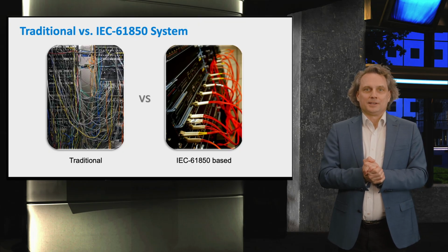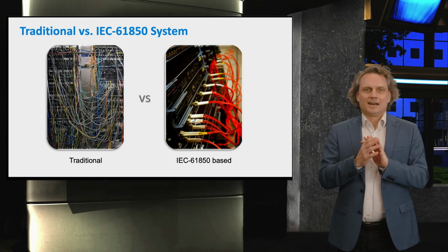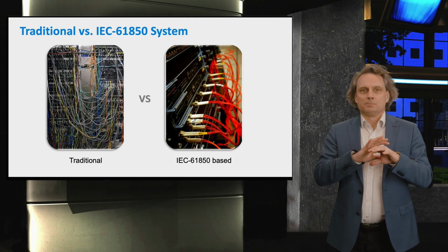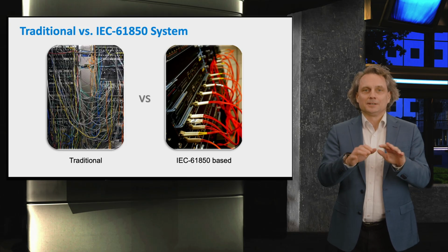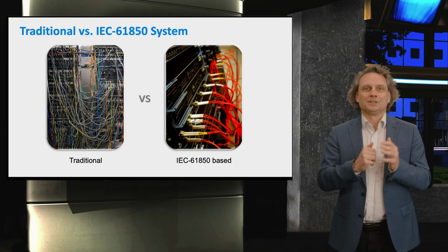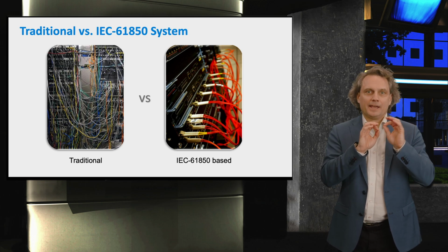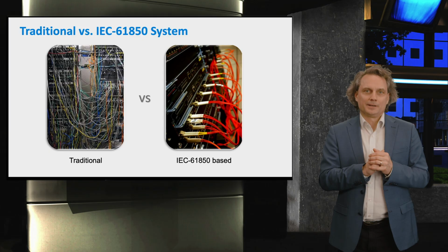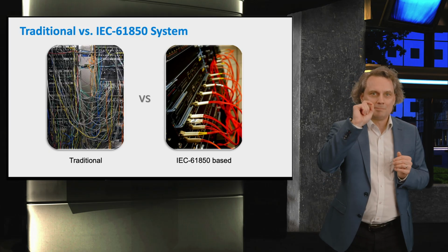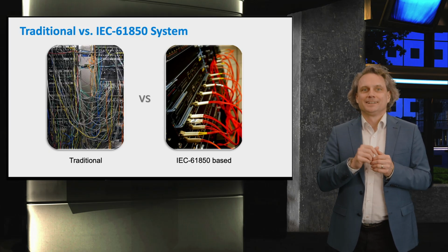What is the impact of IEC 61850? The classical goal is to replace old SCADA and measurement wires with a clear and flexible OT infrastructure. Initially, every sensor and every actor had its own dedicated wire, sometimes even from and to the control room.